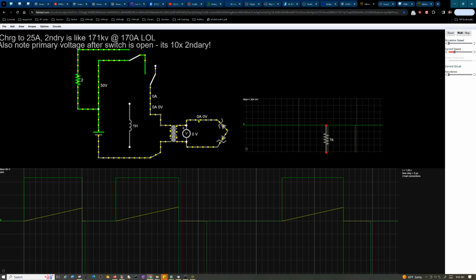You can see what it's doing on the meter, and I do believe that's fairly correct, but the scope isn't. It doesn't have anything to reference against, and that's why it's creating a problem, because it doesn't know what to reference. I don't know if you could just put a ground here, but I tried connecting this secondary over here, and it really just didn't care for that much.